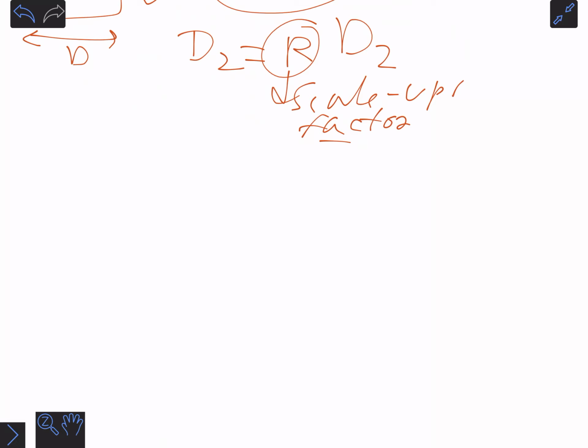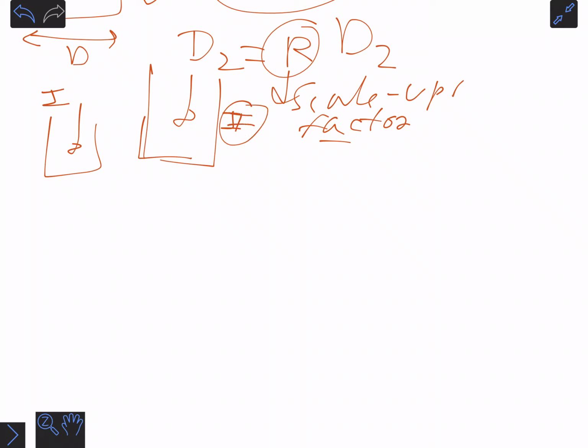So first we find this. Suppose this is a small scale agitator and this is the large scale one. This is tank 1, agitator 1, and this represents agitator 2. Okay, so the volume of the first agitator is pi Dt1 square by 4 multiplied by H1.